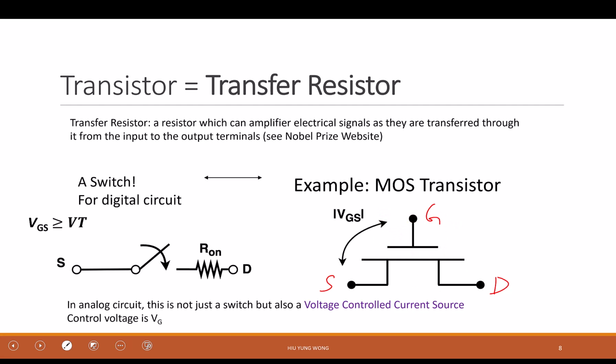And you see that I change the voltage or control the switch at the gate, but the current does not change at the gate. It changes at the source and drain. That's why it's called transfer, right? This is very important because later I will keep asking, what is transconductance? You want to know that when I add something to the gate, how much I'm changing the drain current or drain output impedance, whatever, right?